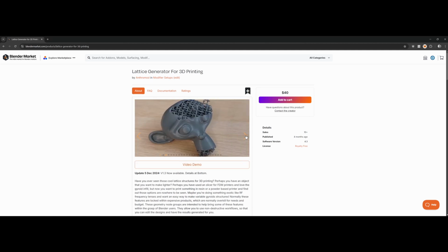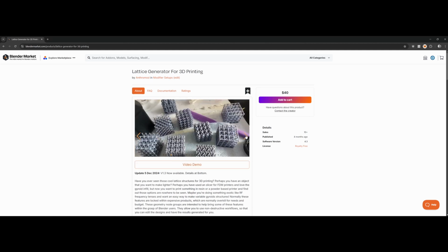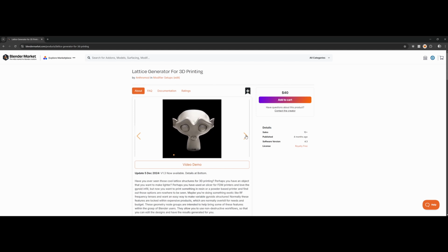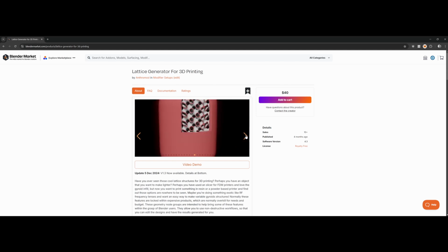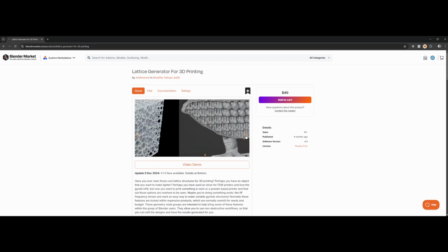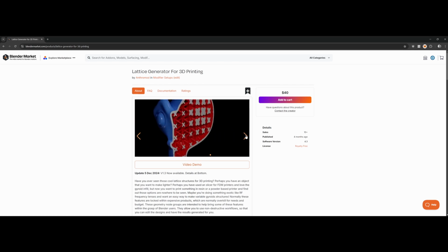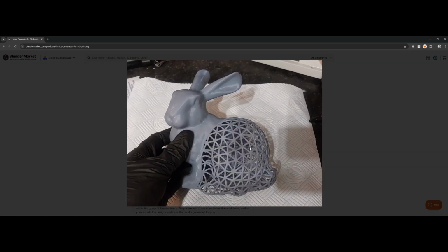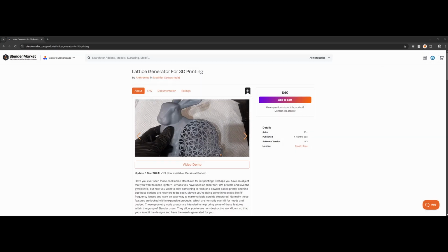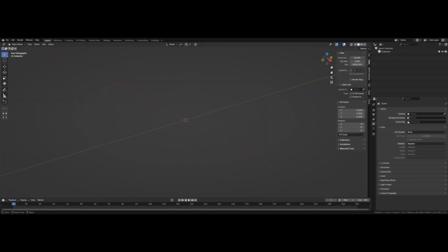So I do a lot of 3D printing work, and I often use Blender to model and prepare a design for 3D printing. However, Blender has lacked a number of tools, which has meant that I often had to export a model out of Blender, perform some task on it, and then import it back in. The biggest task involved altering a model so that a 3D print used less material. So after a few different attempts, I came up with an SDF based method which allows hollowing and lattices to be added to 3D prints.